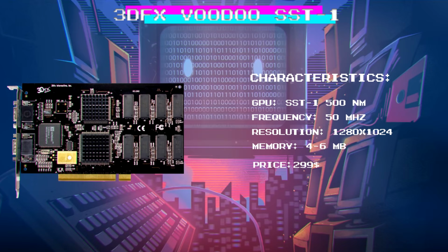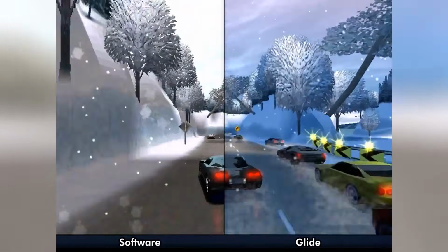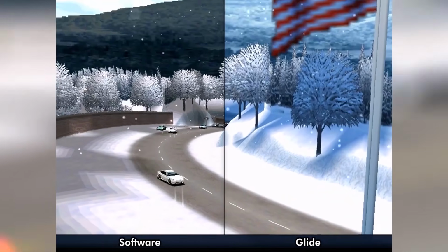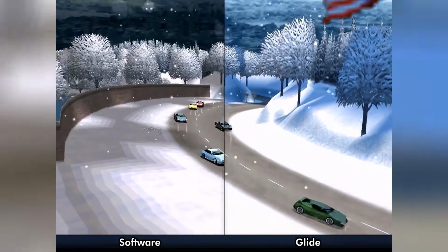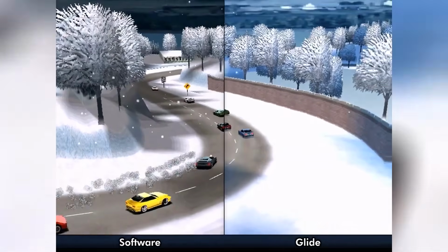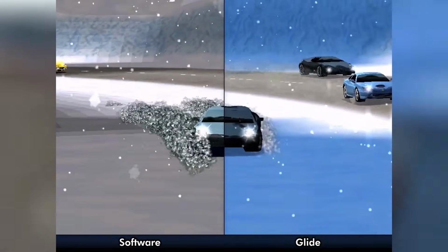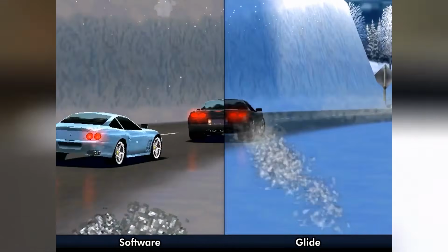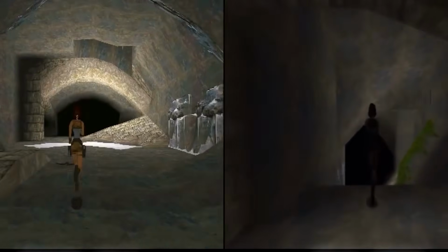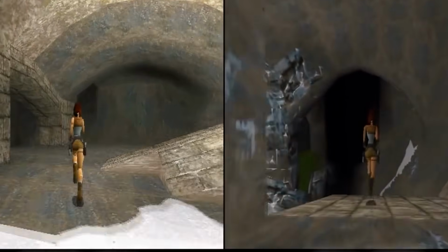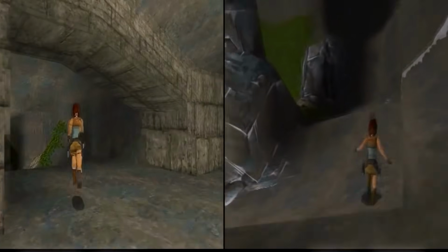Interestingly, Voodoo had a separate texture module, and this architecture allowed the video card to work quickly and display a very high quality picture. The only drawback of Voodoo was that the video card worked exclusively with three-dimensional content, and for processing 2D graphics, the system required another accelerator. Therefore, in the mid-90s, a combination of Voodoo and Virge graphics cards was especially common, the first having tremendous performance in games and other applications related to 3D graphics, and the second in programs with two-dimensional images.